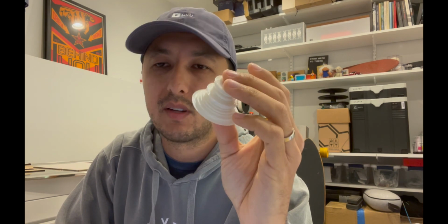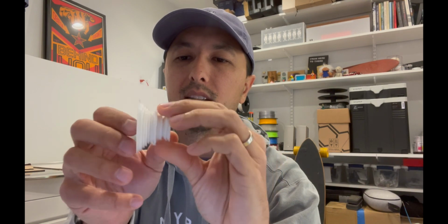So if you're doing tests, maybe reduce the percentage for the infill to speed up the job. But yeah, the 20% seemed pretty good. You probably could knock it down a little bit more if you wanted to. But because of the fineness around the rings, it doesn't look all that perfect. But again, this is just kind of a prototype, and we can use other methods or send it out to get printed for something that's a little bit nicer and made out of nicer material.